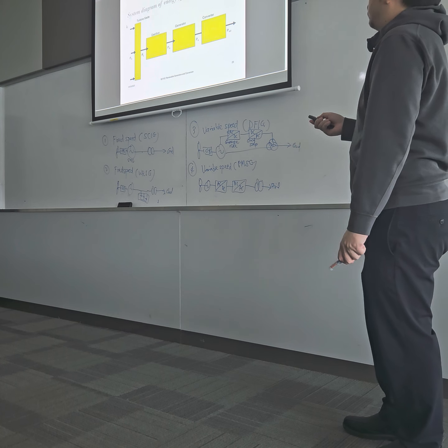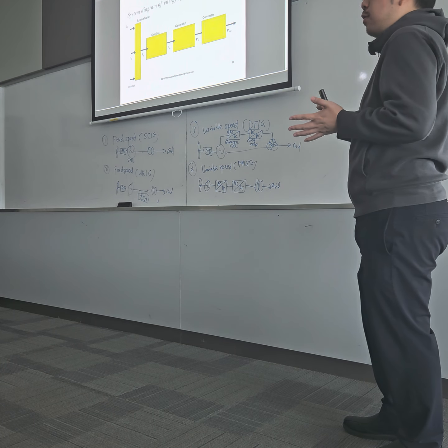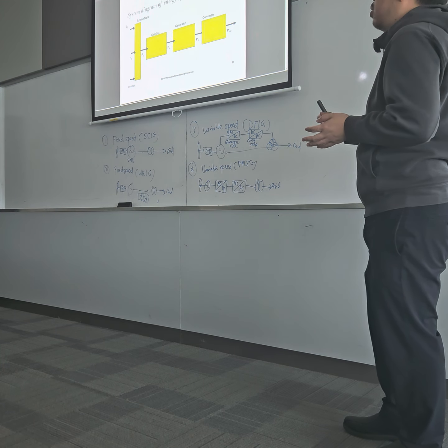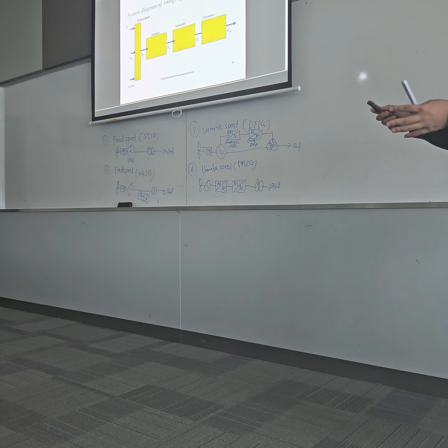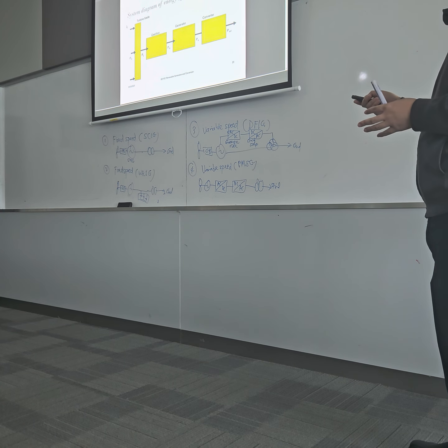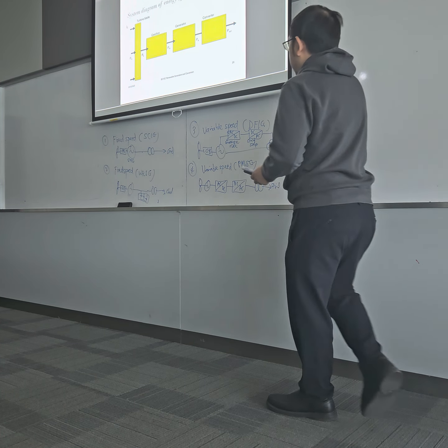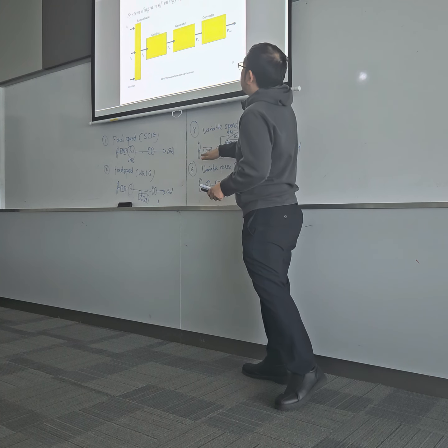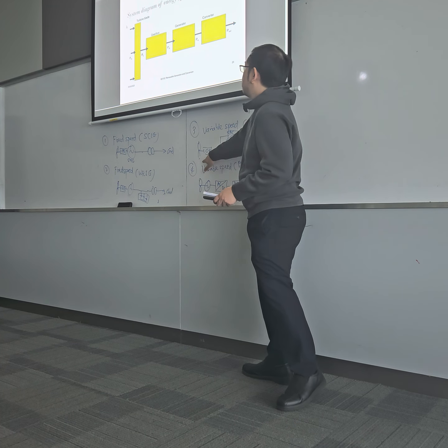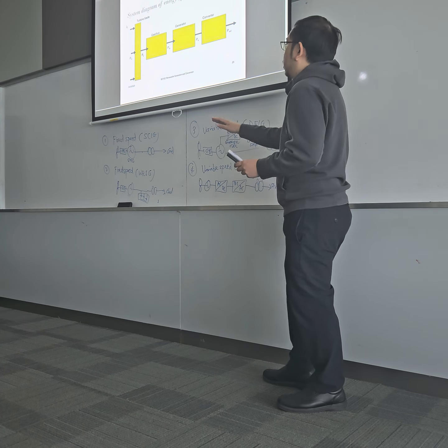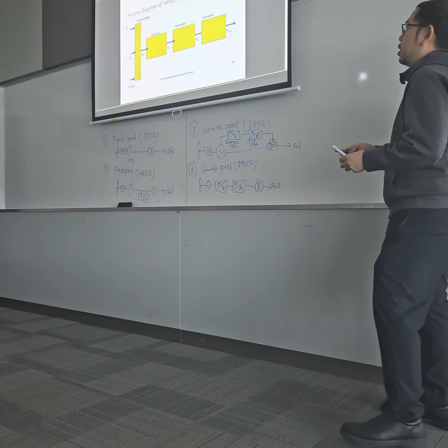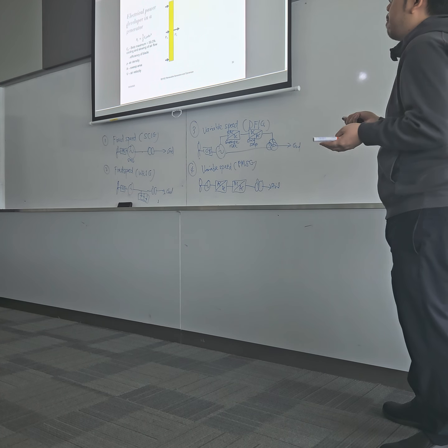Okay, next we'll move on to the energy power conversion. This one will calculate the overall efficiency of your system. Say you have the few components that we have covered just now: the turbine blade, gearbox, generator, and converter. All of these have a certain efficiency.